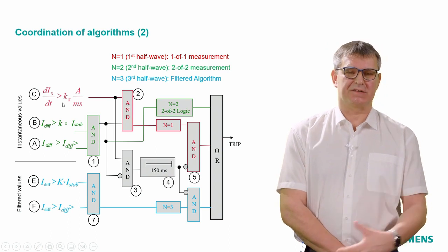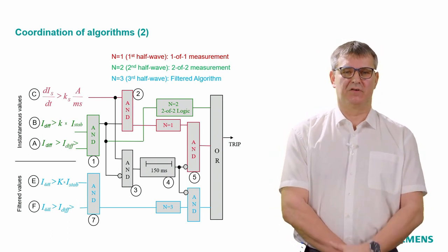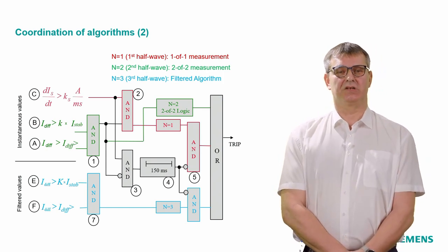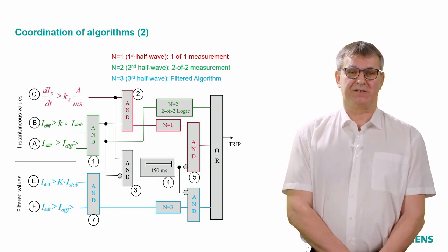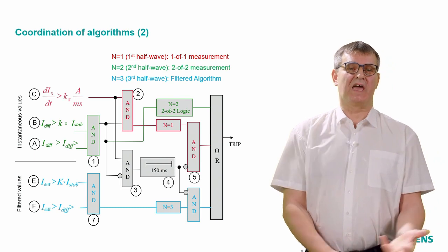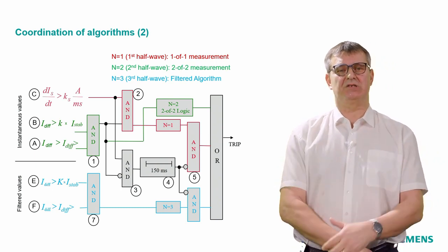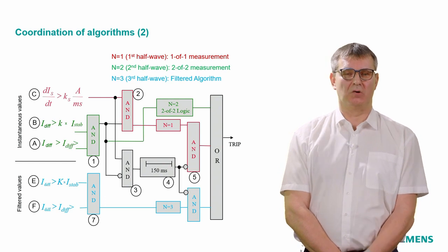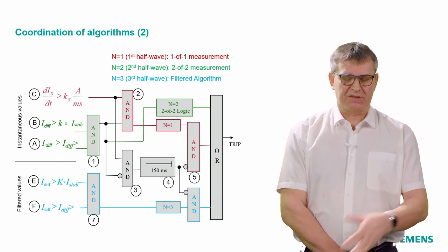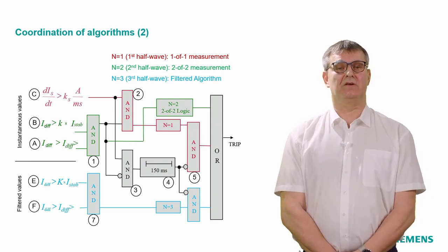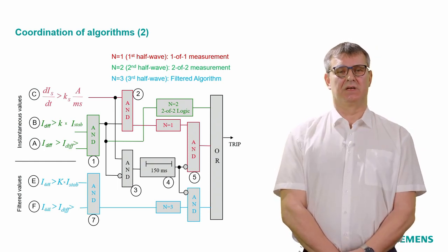And some guys answer it's an external fault, some guys answer it's an internal fault, and some guys are right, as hopefully also you. We have no idea. A jump of the stabilization current, criteria C, could be both. A jump of the stabilization current will happen both in case of an external fault and also in case of an internal fault.